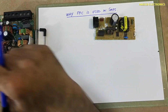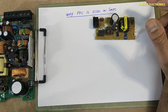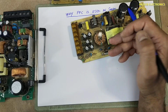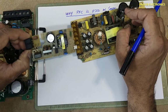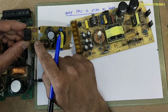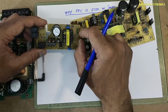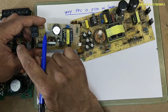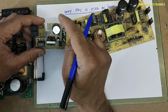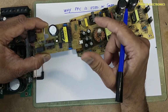If we see this universal power supply, it is providing 5 volt 2 ampere. If we see this power supply, it is providing 12 volt 20 ampere. The difference between this power supply and this power supply is that we apply 85 volt to 265 volt. So this power supply will produce 5 volt 2 ampere with this large variation in the voltage, from 85 volt AC to 265 volt. It will provide regulated output with minimum load or with maximum load.